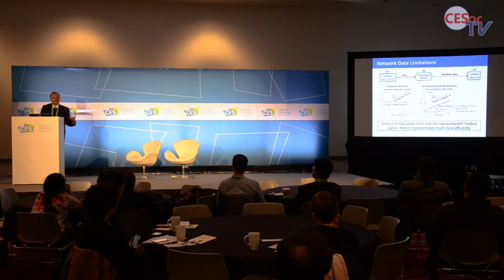It's really the transmission energy. So if I have an ECG sensor that is transmitting 10,000 times to my smartphone per second, that transmission energy could be about 99.9% of the sensor energy. So if we could somehow do more intelligence locally and transmit less, we can save a whole lot of energy while making the sensor smart.